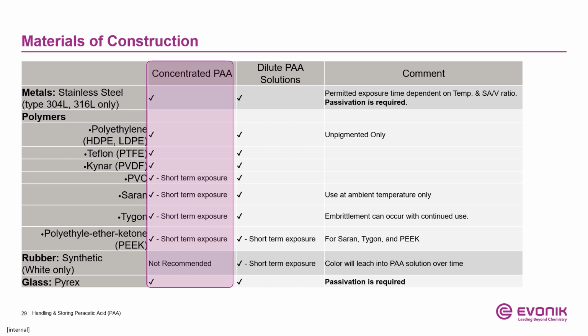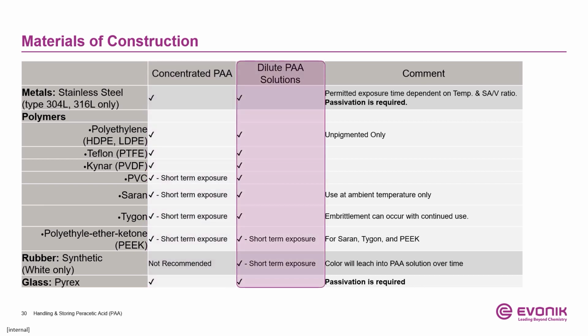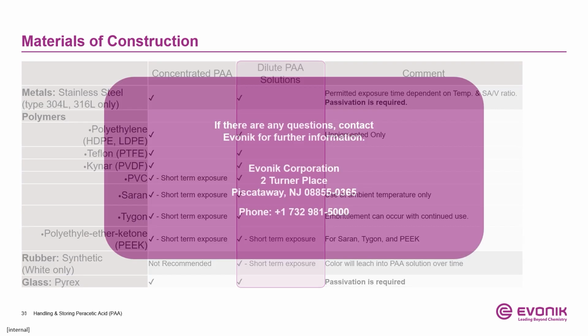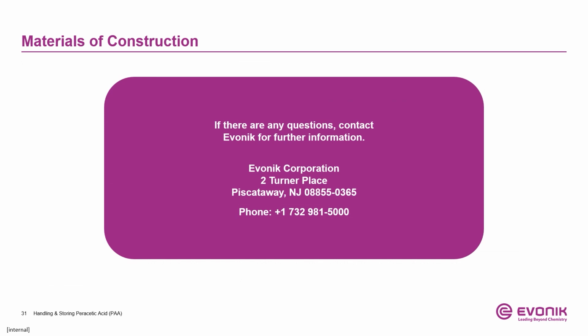Some materials are compatible with concentrated PAA, while some materials are only recommended with the diluted product. Additionally, some materials may only be suitable for a short-term contact. If there are any questions regarding materials of construction for PAA service, please contact Evonik for further information.